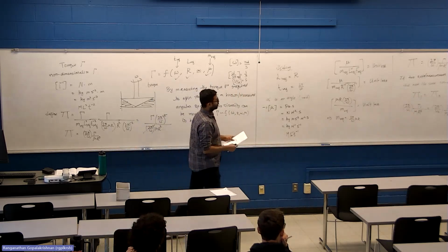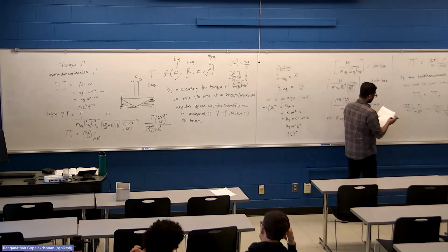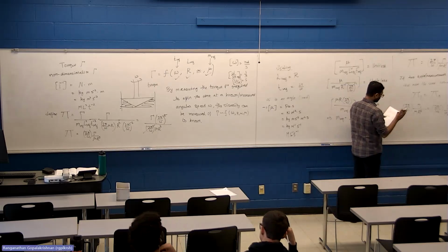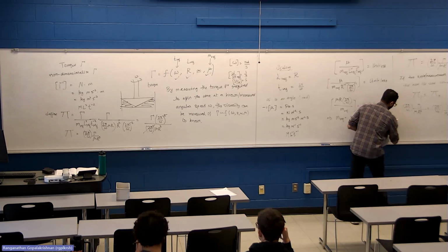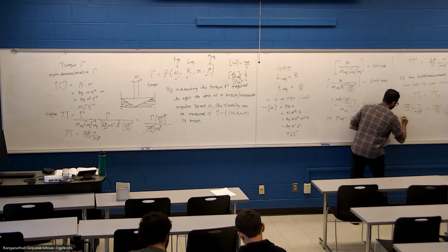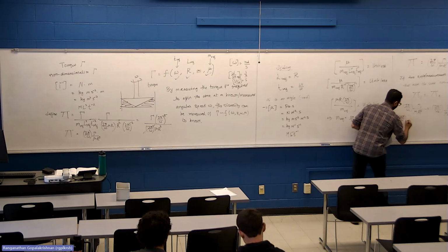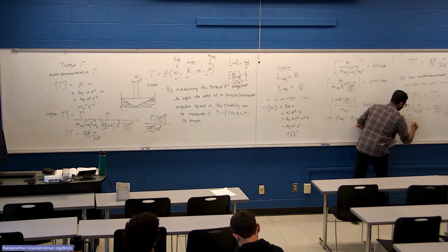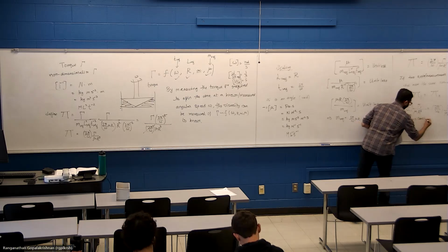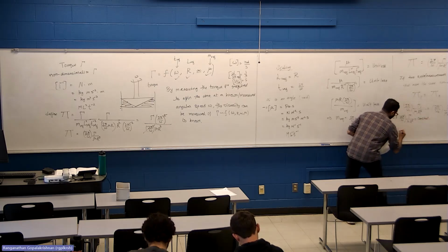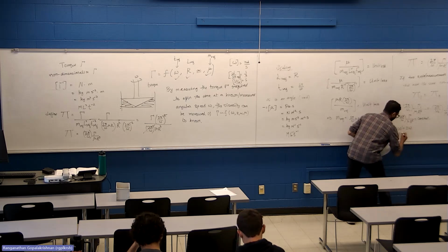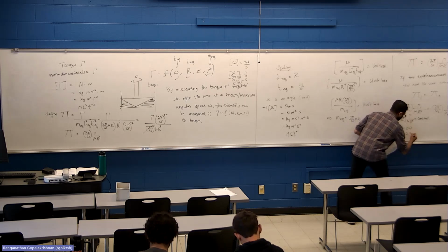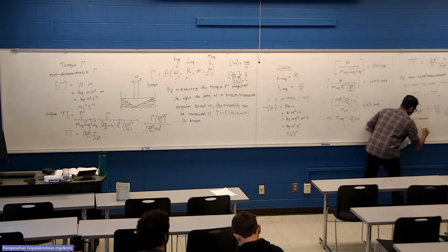Okay. So the question is, what will happen to the torque if both the viscosity and angular velocity are doubled? What will happen to torque? So if 2 pi over omega times gamma over mu r cubed is a constant, and I replace omega with 2 omega and mu with 2 mu, what should be the new value of torque?